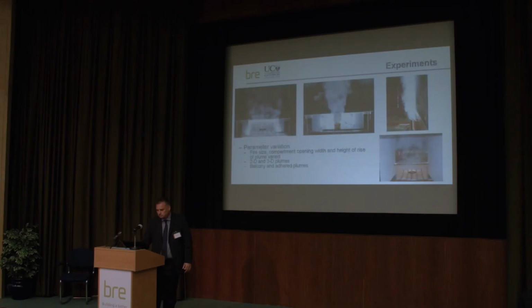In terms of the experiments, again, as I've said, over 300 were carried out. I varied the fire size, the compartment opening. This is the equivalent of around 10 meters wide. This is more like a doorway opening, around 2 meters wide. The plumes look quite different, as you notice.